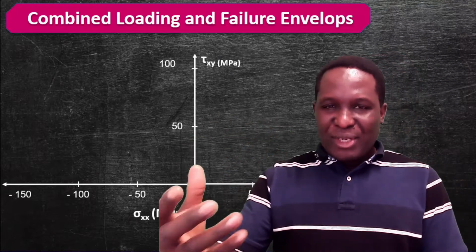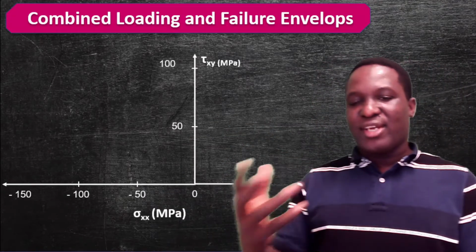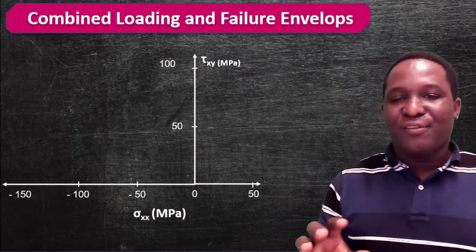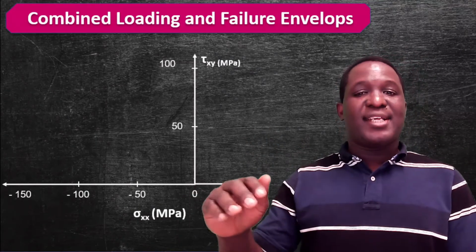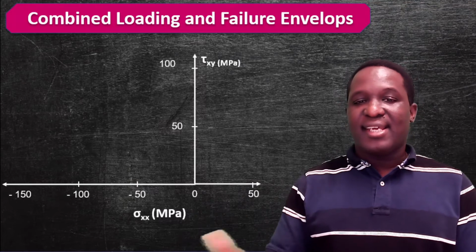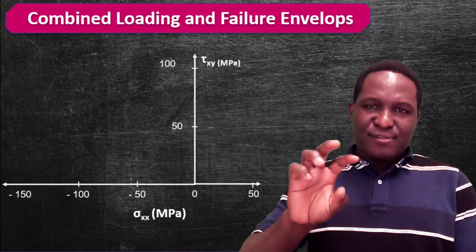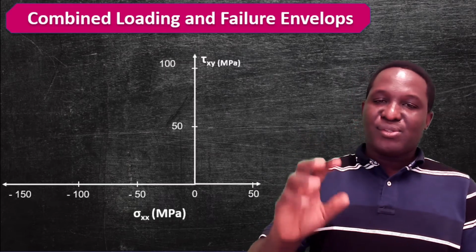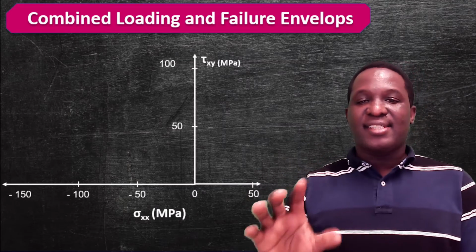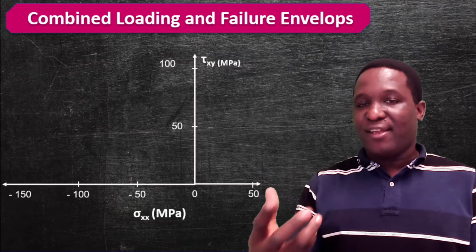So Dan went on to explain that what you're trying to really do is think about your failure as a two-axis problem. There is a horizontal axis, which is probably a stress axis, and there is a y-axis. So you have two stresses interacting at a point. And every time these two stresses interact, depending on their size, they will lead to a point of failure.